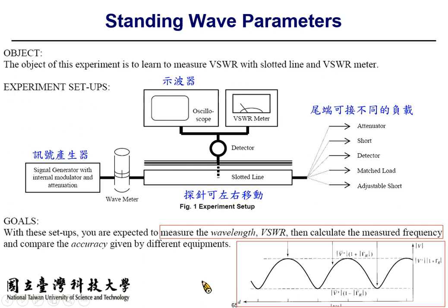And you may question that if you have a slot on the rectangular waveguide, will it radiate energy? Well, if you cut the slot in the middle of the rectangular waveguide, there will be no radiation because of the boundary condition. Because at that point, there will be no horizontal electrical field across the slot, which means there will be no radiating E and H field.